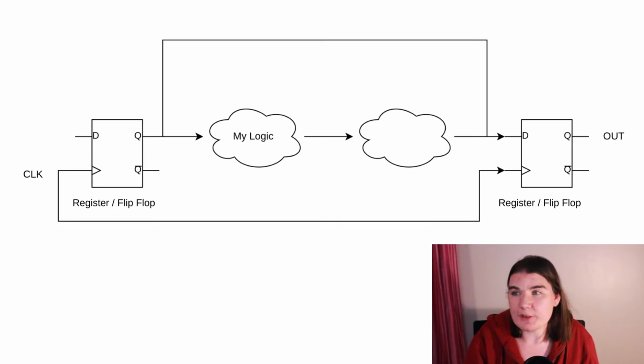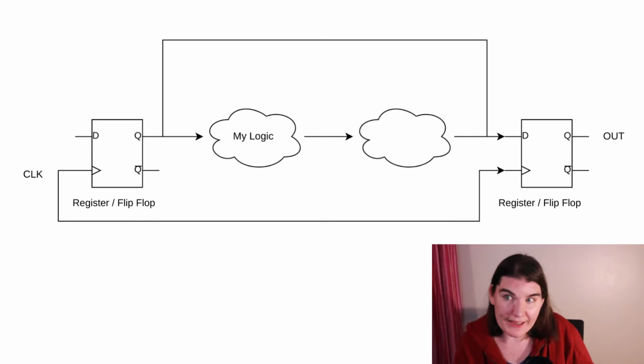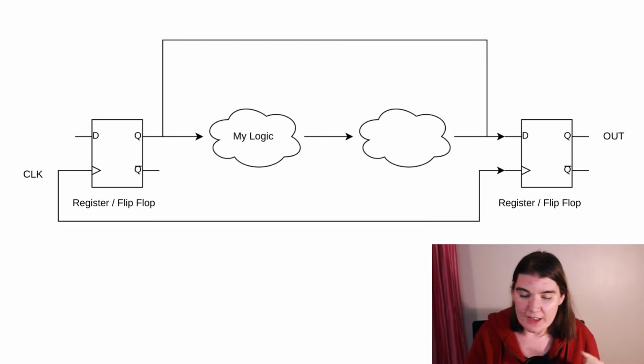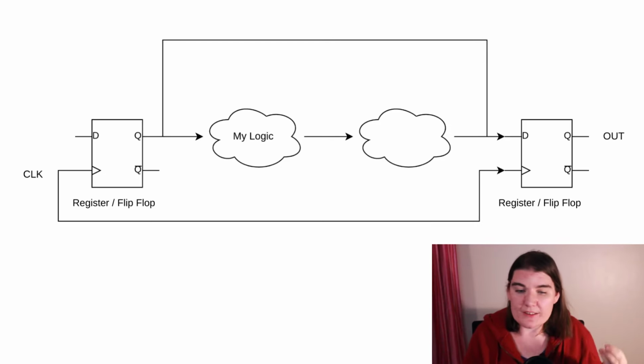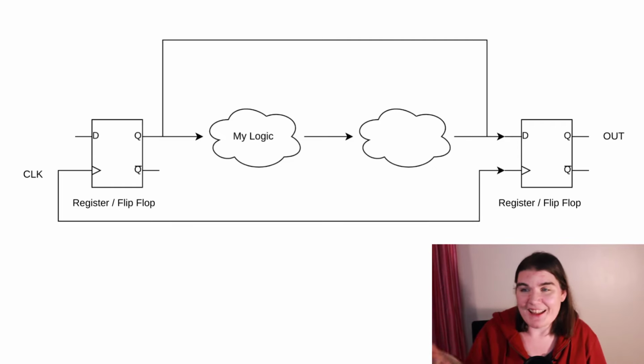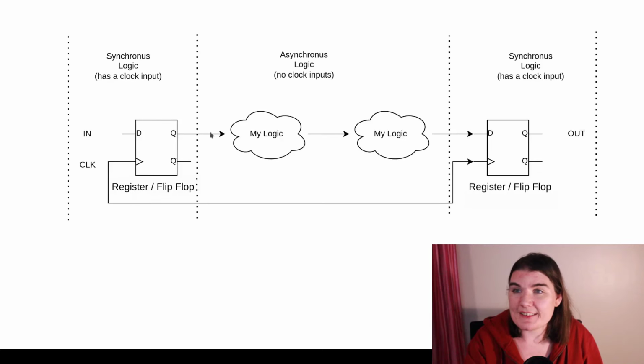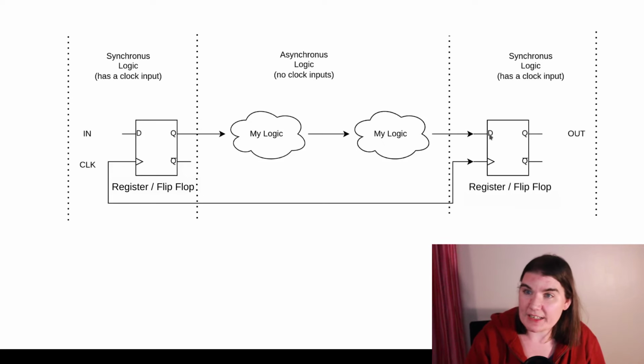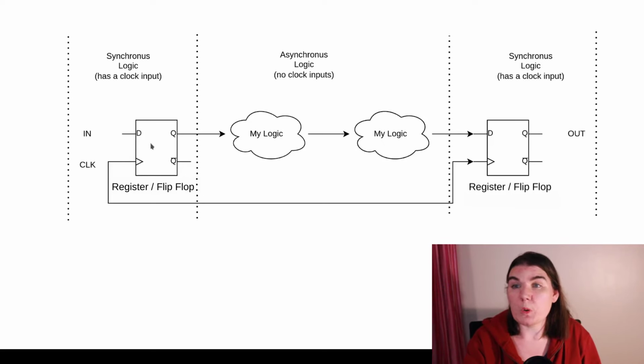What happens if we do this? So now I am feeding a signal back inside my asynchronous logic. The static timing analysis tool that I mentioned measures the signals of the path. If we go back here, it's easy: you start there, you end there, you've got this length of the path, and the static timing analysis is going to take the lengths of the paths from one memory element to another.